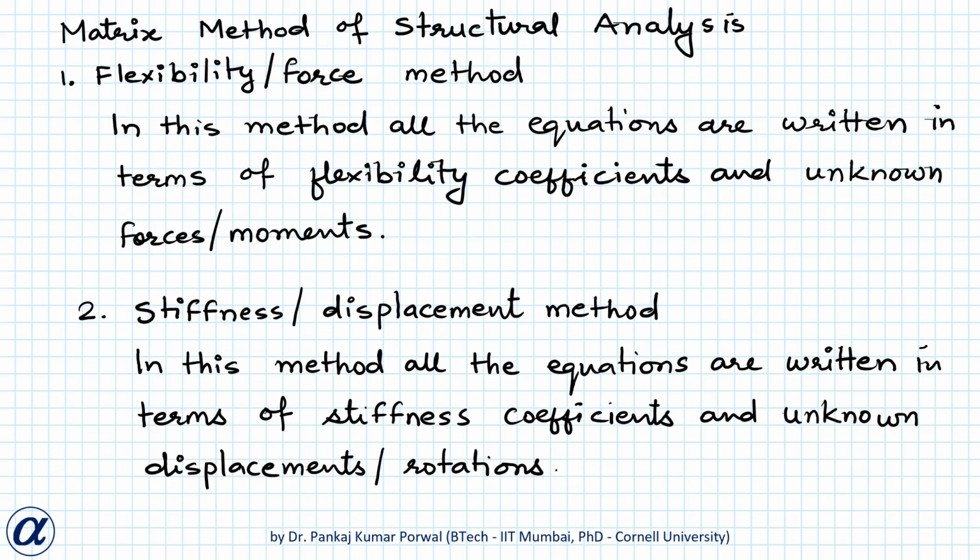In this session, we are going to learn about matrix method for structural analysis. There are two approaches that are commonly used in this method. First one is flexibility or force method, and second one is stiffness or displacement method. In flexibility or force method, all the equations are written in terms of flexibility coefficients or flexibility matrix and unknown forces or moments, and that's why this approach is called flexibility or force method.